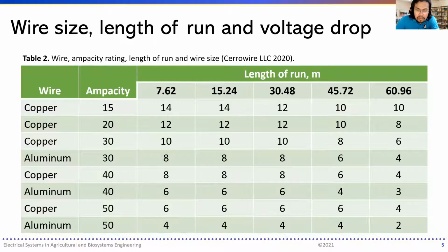Now, to determine the load, add up the wattage of all electrical devices that will be on the circuit and divide this total by the voltage of the circuit, usually 120 volts or 240 volts. If it's bigger for a three-phase, then do so. Now, the tables assume steel conduit, a power factor of 0.9, an ambient temperature of 86 degrees Fahrenheit, and no more than 3 current-carrying conductors.